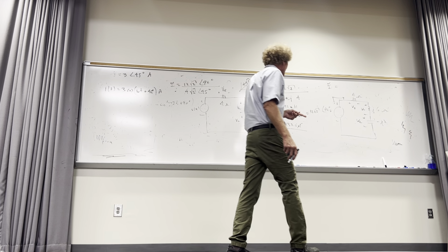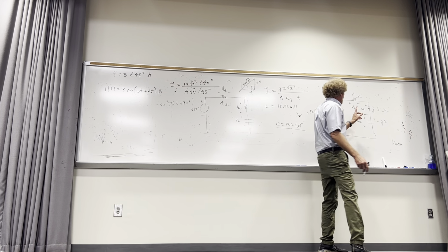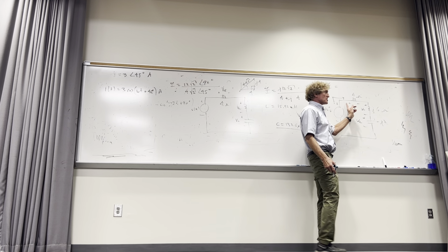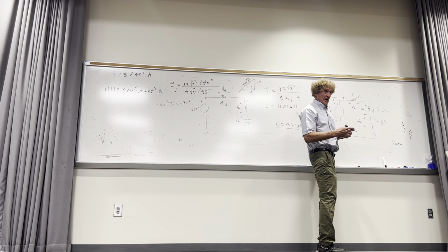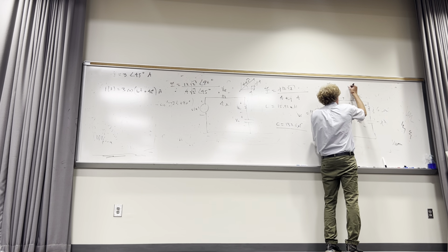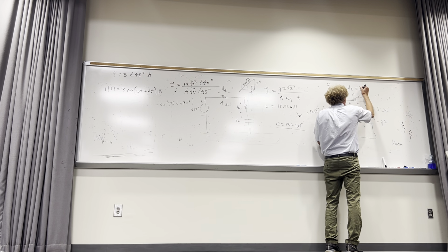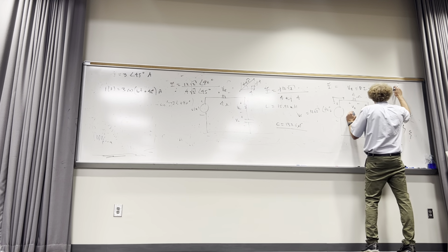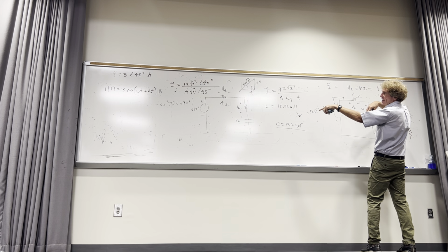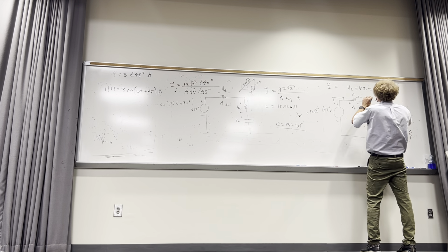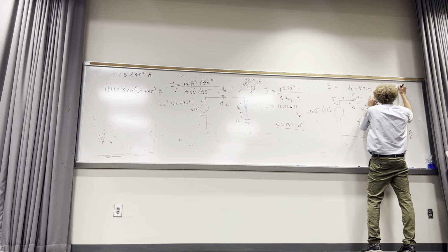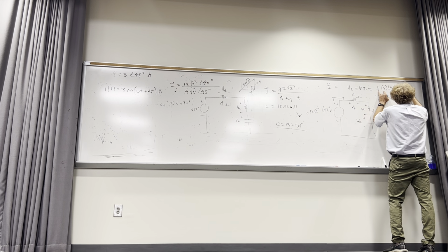All right, now let's get this voltage. First, do we know the current? Yes. What would this voltage be? Just R times I, right? So V of R is equal to R times I. R is 4. The actual current is 3 at 45, so it'd be times 3 at an angle of 45 degrees, or 12 at an angle of 45 degrees volts.